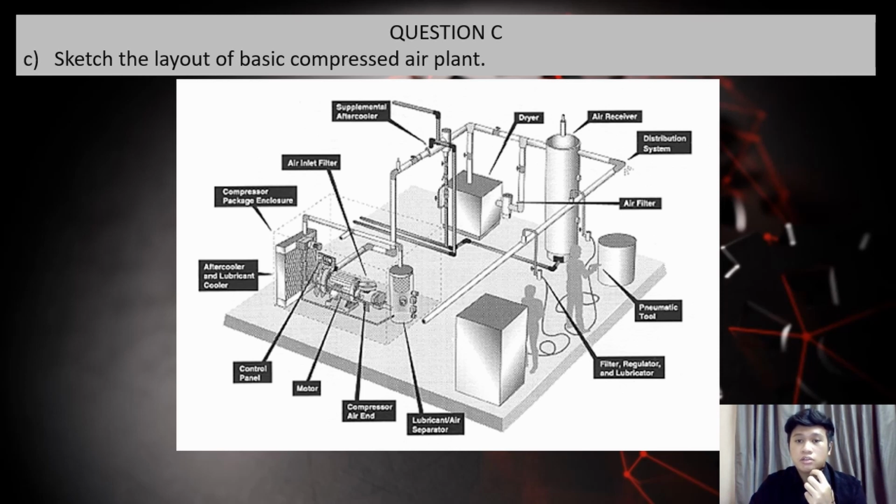Aftercoolers remove the moisture in the air by reducing the temperature in a water cooled heat exchanger. The remaining traces of moisture are removed using air dryers, as air for instrument and pneumatic equipment has to be relatively free of any moisture. The moisture is removed by using absorbents like silica gel, activated carbon, or refrigerant dryers, or heat compression dryers.